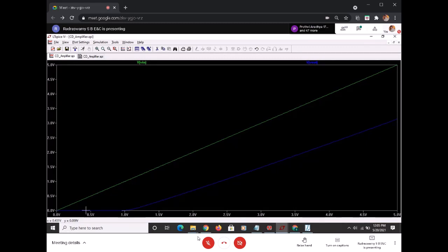I can't consider the biasing voltage to be 0.5 because the output is not following the input. I can't consider 0.1 volt as the biasing voltage either. At 1.4 it is starting, but you can see that it is not exactly following. At 1.2 it is still not parallel. At 2, 3, 3.54, I can now have the biasing voltage with respect to the DC biasing of M1. Somewhere after 4, they are approximately parallel. Not exactly, but this is better than this now.